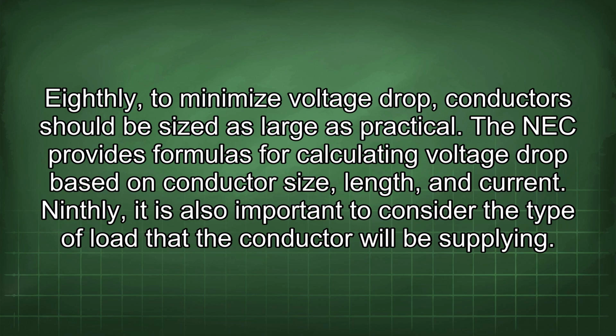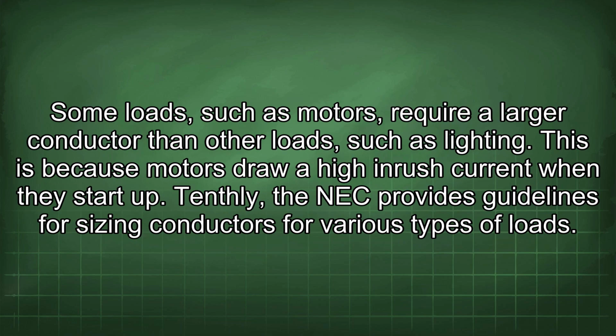Ninthly, it is also important to consider the type of load that the conductor will be supplying. Some loads, such as motors, require a larger conductor than other loads, such as lighting. This is because motors draw a high inrush current when they start up. Tenthly, the NEC provides guidelines for sizing conductors for various types of loads.